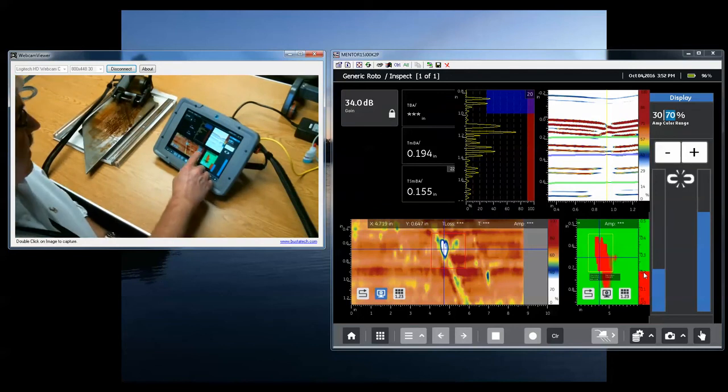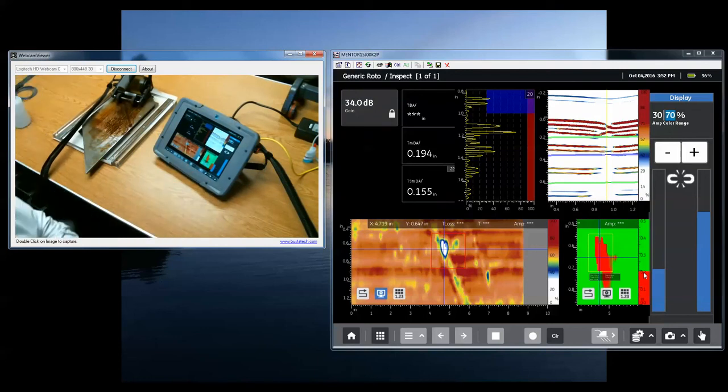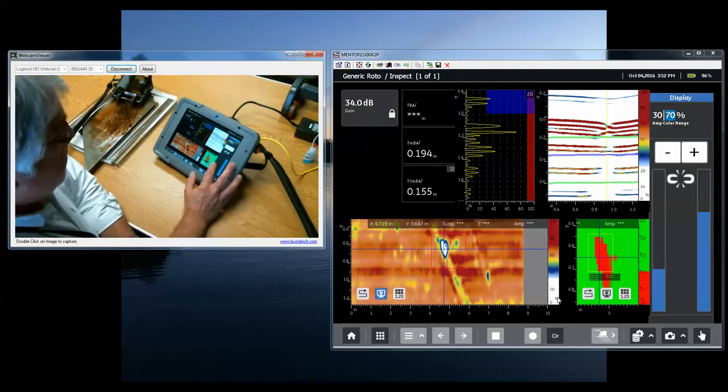So if you notice, the upper end of my palette was red, so now a larger region of the ruler is showing red on this C-scan. I set the bottom of the palette to 30%. Everything below 30% is the white color that is the 0% color of the palette itself.